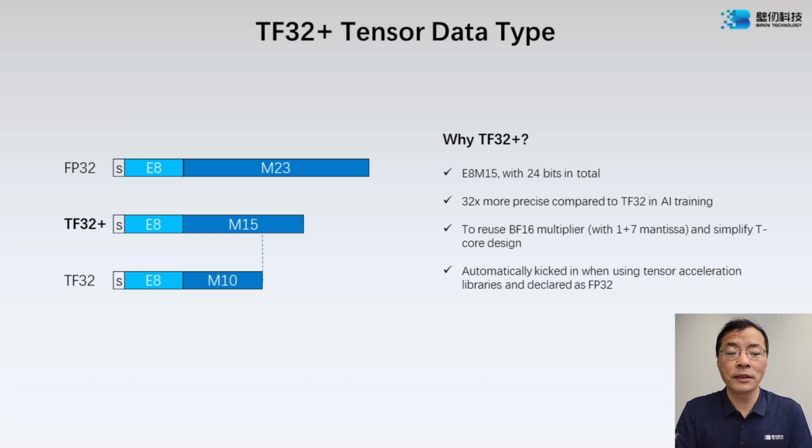We have an efficient FP32 tensor implementation. We can have 1/4 of BF16 flops performance with FP32. That means we can achieve 256 teraflops with FP32. NVIDIA FP32 tensor performance emulated with 3x TF32 can only achieve 1/6 of FP16 performance.